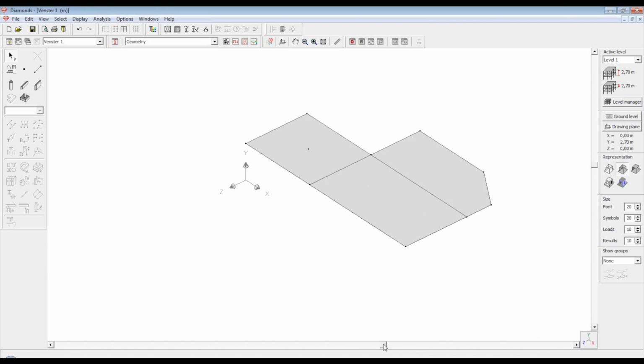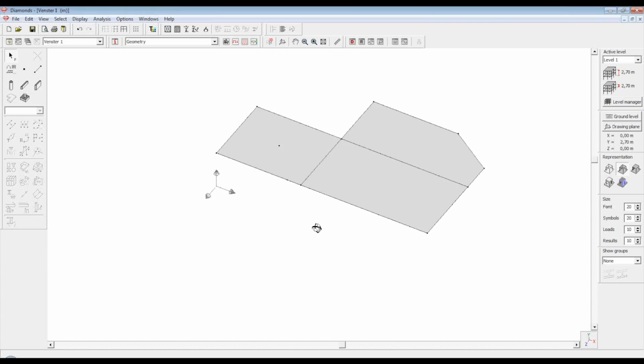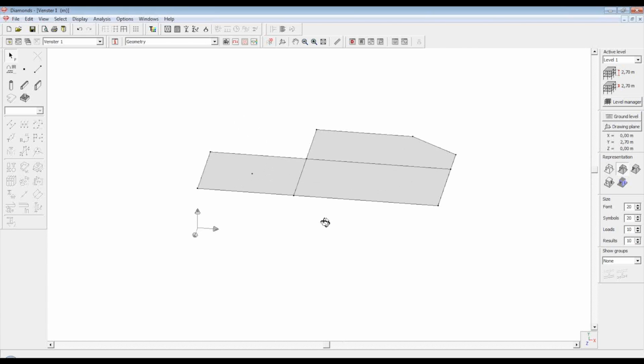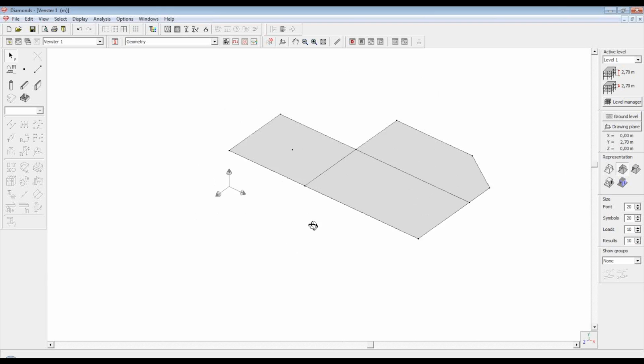Alternatively, you can rotate the model with the 3D orbit function. So hold the Shift button down together with the scroll of the mouse, and you will see the shape of the cursor of the mouse changing into a 3D orbit one. And when you move the cursor or the mouse around now, you will have the 3D orbit function.